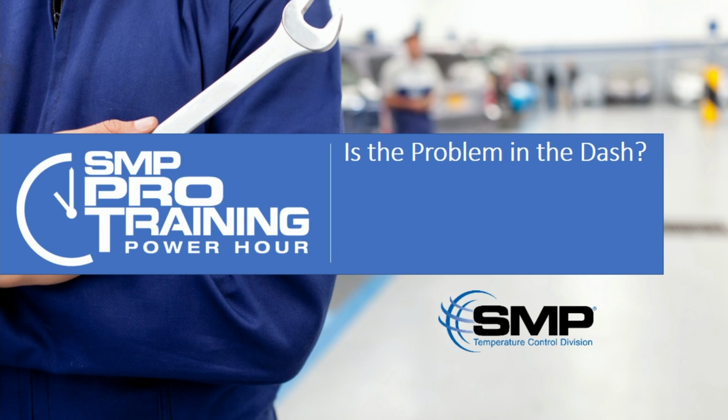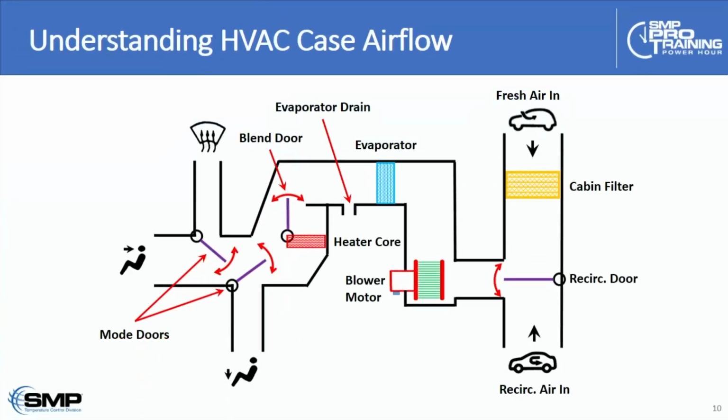And often it's important to really satisfy that the problem is actually in the HVAC case or in the dash. So just for the record here, this is a kind of simplified airflow schematic of a typical HVAC case. You can see over here on the right hand side, the air can either come in from the outside if we have the button set on fresh air, or we can draw it from inside if we have it set on recirc.